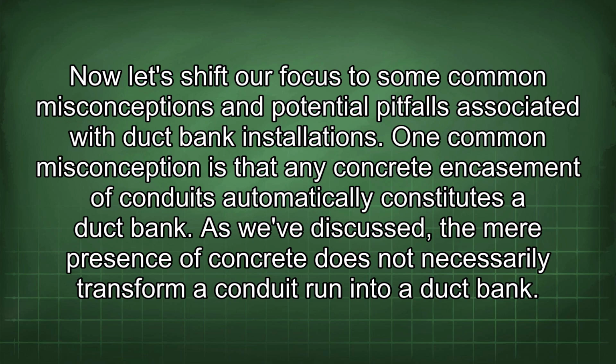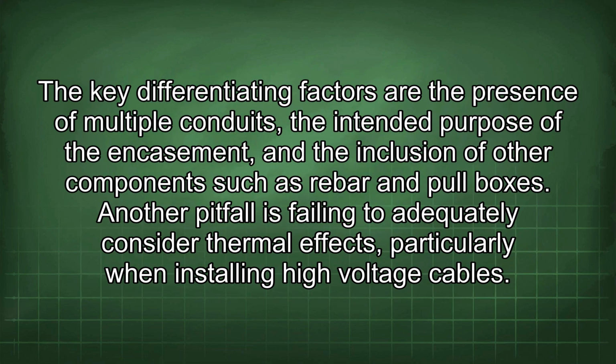One common misconception is that any concrete encasement of conduits automatically constitutes a duct bank. As we've discussed, the mere presence of concrete does not necessarily transform a conduit run into a duct bank. The key differentiating factors are the presence of multiple conduits, the intended purpose of the encasement, and the inclusion of other components such as rebar and pull boxes.